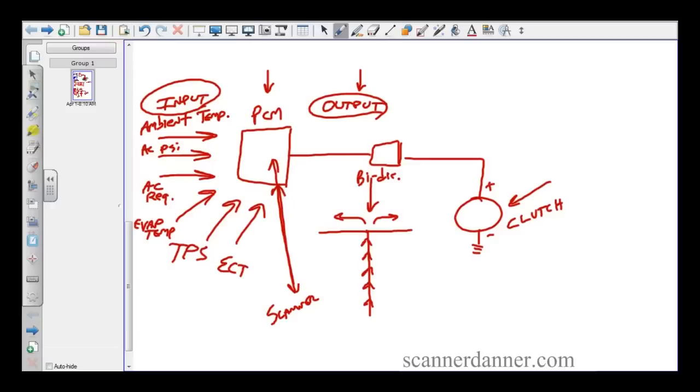If that AC clutch over here turns on, how is everything from this side over? It's good. Leave all your test light and voltmeter, all that other stuff in the toolbox for that entire output side. Have we just eliminated a ton of checks?